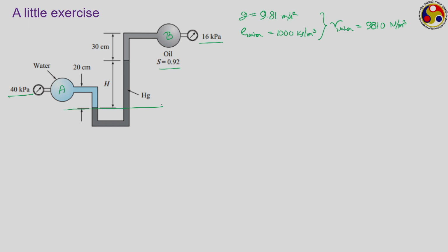Like in this case, below this particular line, this entire portion corresponds to only mercury as the fluid, and so we can neglect this because we know the pressure at this point and this point has to be equal, and that is given by equal height of mercury column on both sides. So, how much is the pressure? Let us say this is position 1 and these are position 2. So, pressure at point 1, how much will it be?